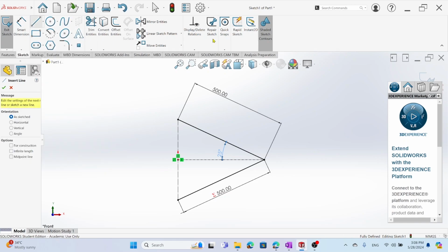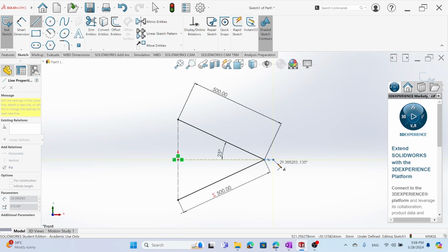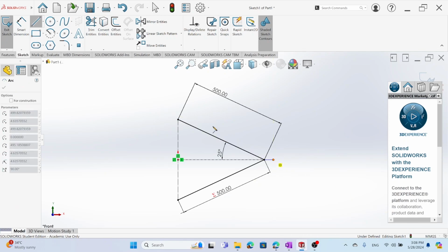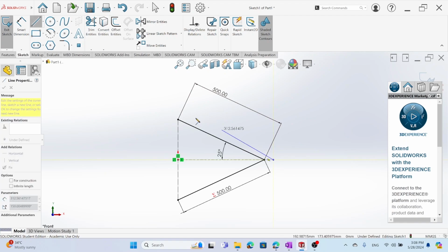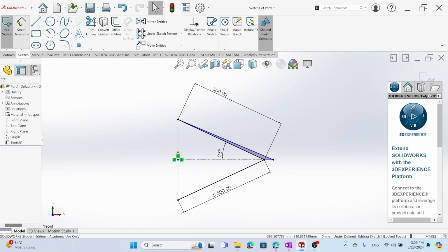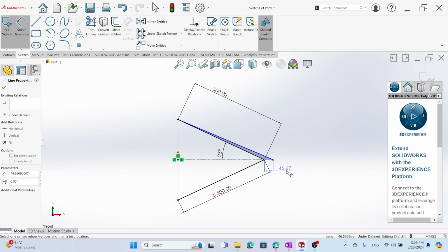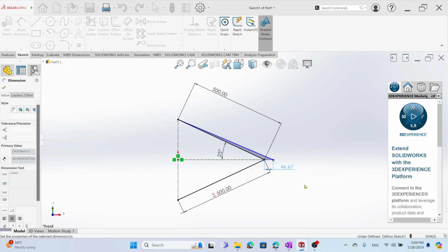And I will add another line that represents just the displacement of the point A. So I will go from this point to this point. That's my displacement. And I will add another line. Need to go back there. Okay, let me escape and do it again. And I will add a line from the point, let's say A prime to that point. So that's the stretched cable. So the cable will stretch all the way there. Here we go, escape. And I will add the dimensions of this one. Let's say it's moved 5 millimeters.